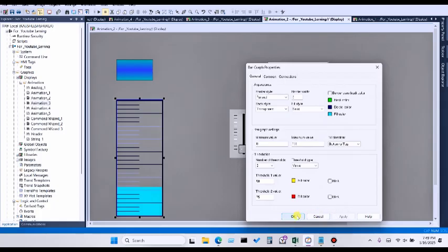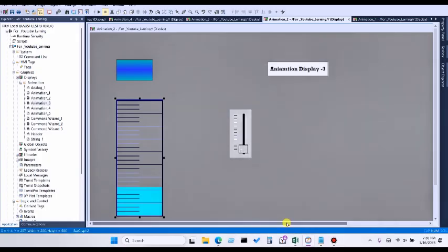One thing, for example, you have to change the threshold color. So what you have to do, change the threshold color from here, 0 to 50, or you can choose 25, and also you can choose 50. It will show yellow color after 25, and red color after 50. But red color after 50 is not required, so you can select 25 and 75, it is better. Click on apply and OK.